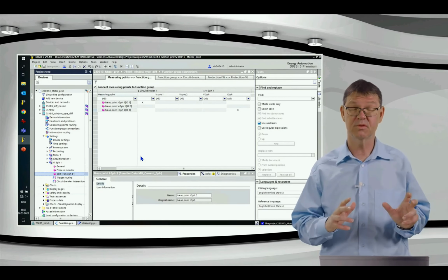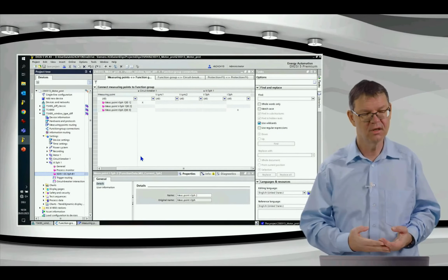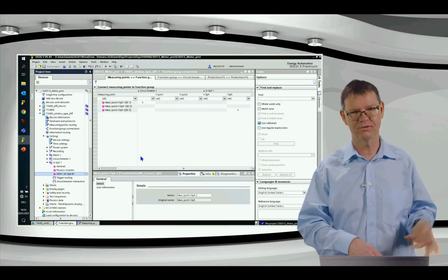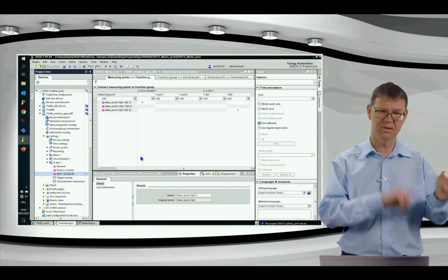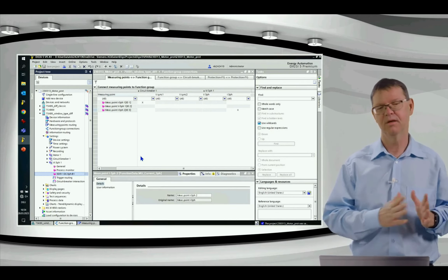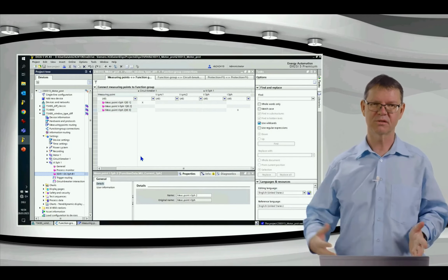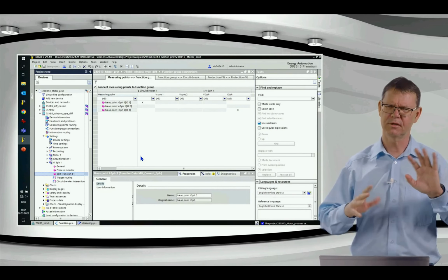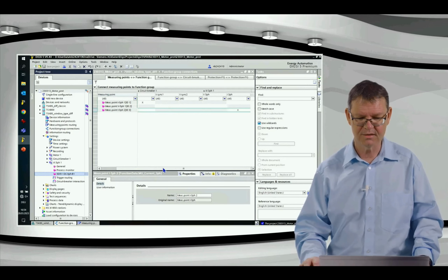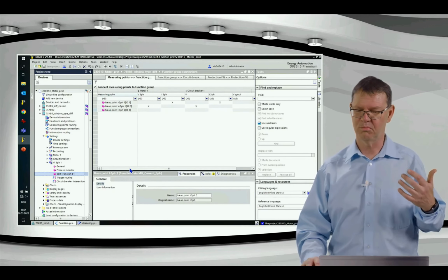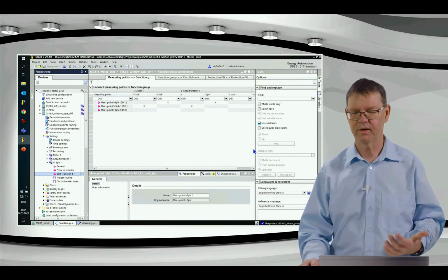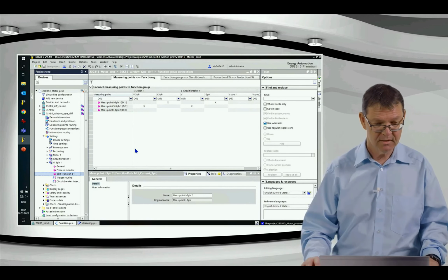I know for the classical overcurrent protection, we can at least protect 10 feeders with overcurrent, directional overcurrent, auto reclosure, synchro check, I don't know, but breaker failure protection. So not only just a very basic setup, but already a relatively big scope, times 10. I think the limit is 12, but I don't remember exactly. And in a similar way, I think this could be possible also for motors. So just to show you a little bit the power we have with SIPROTEC 5 relays.